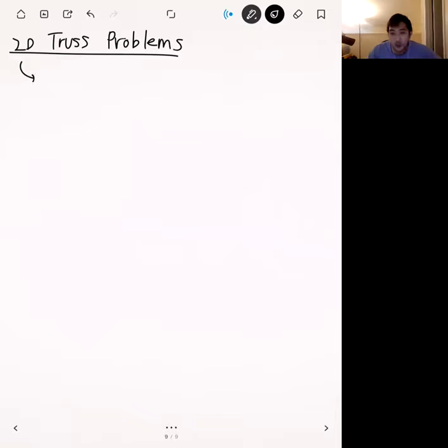All right, and so beams that we just covered, we know that they experience transverse displacement and also rotations, and so truss elements will basically just support compression and tension. In other words, one way that we can describe that is truss elements can only displace axially, or down the length of the element.